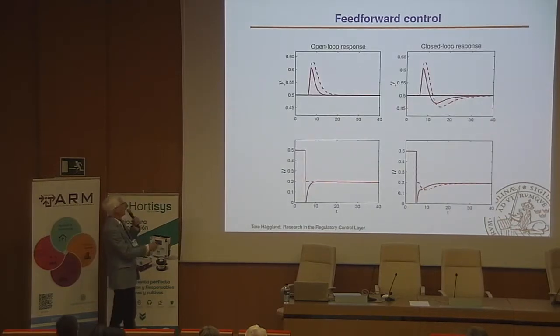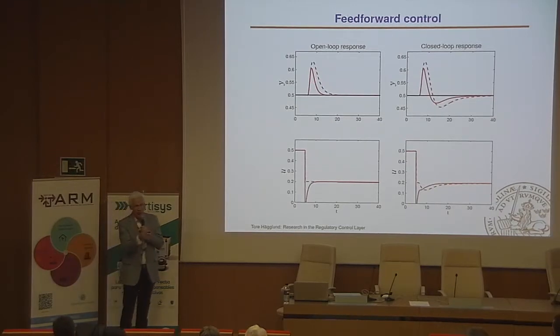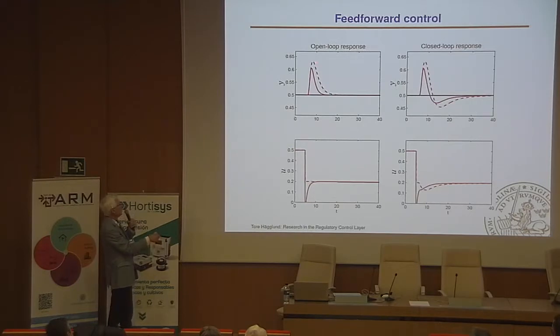Look at these two. Here we have a simulation example with a low disturbance. We have two compensators, a static one and a lead-lag, a compensator that is a pole and a zero. Look to the left. The dashed line is just a static compensator, a gain. We get the disturbance, the feed forward jumps down, and this is the response we get. If we have a lead-lag compensator, we get an improved response, the solid one.